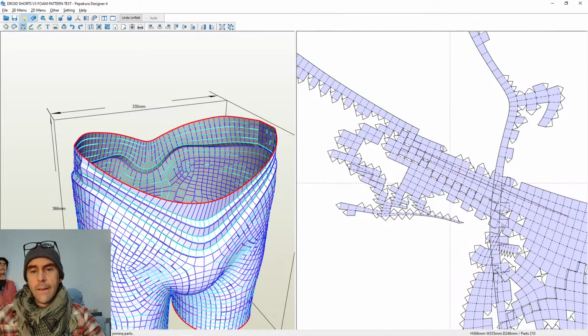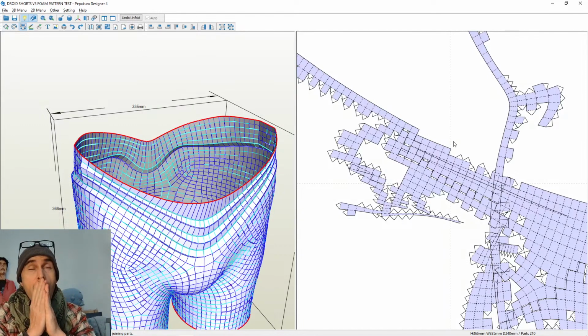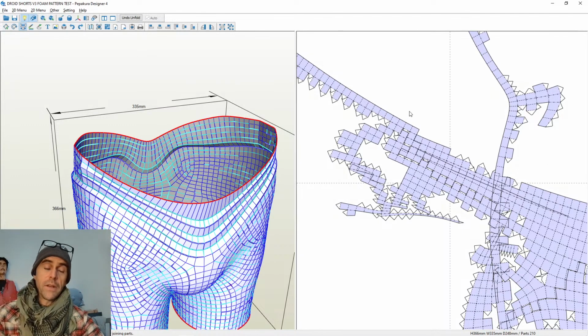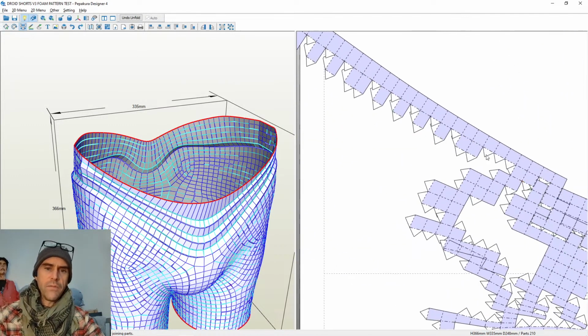Very toxic, so you don't want to breathe it. You definitely wear a respirator or have good ventilation, or both, preferably. But it's really good. There are some other contact cements that are also good. There's one called Weldwood that's almost as good as barge, but it's a little easier to get.